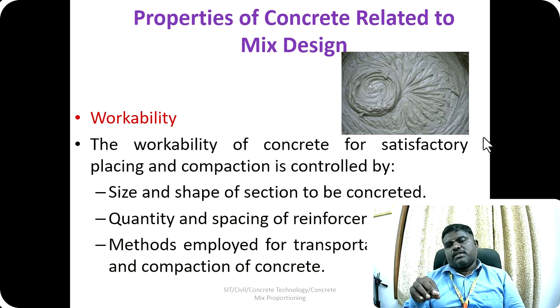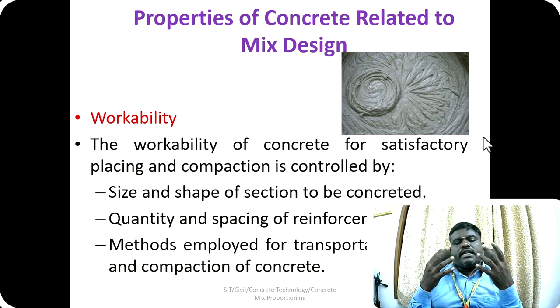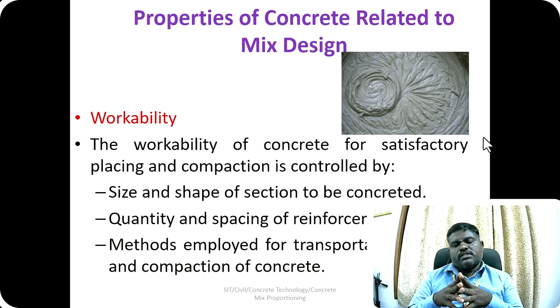For that purpose, we will not increase the water cement ratio, but at the same time we will add some admixtures or superplasticizers for achieving the required workability. The second one is the quantity and spacing of the reinforcement. So based on the spacing of the reinforcement, we will decide the workability of the concrete. If the spacing of the reinforcement is congested, for example, in the case of reinforcement for the slabs and all, the reinforcement spacing will be congested.